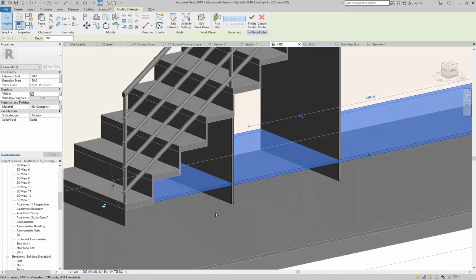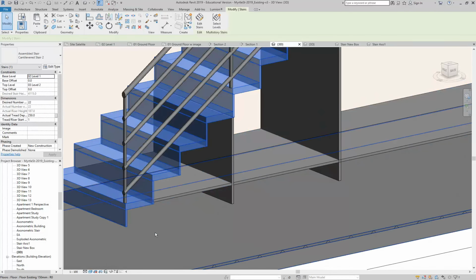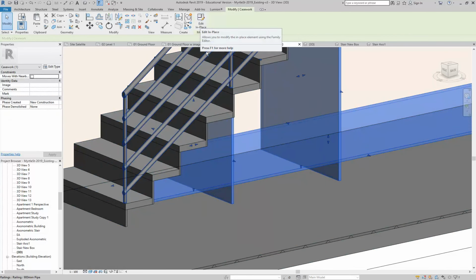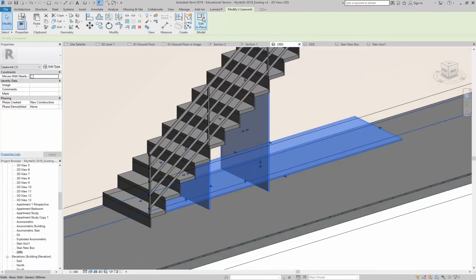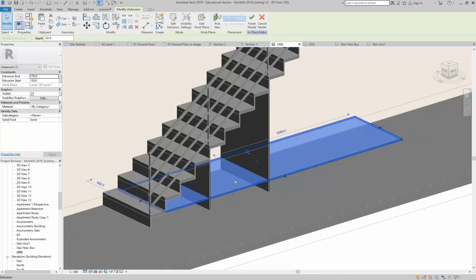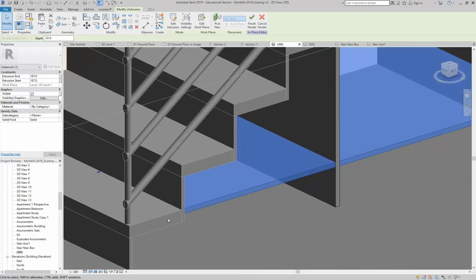So how do you check that? Go and have a look at your stairs. And we can see it's 187. So remember, when you're working with things that you've modelled, you need to go to Edit in Place to change them. Don't go back to Model in Place. Okay, so here I could start, also I'll end at 187, and then I'll come down 20mm from there. So this will be 167. And that's going to line up exactly. Or I could try and even make the thickness of the shelves the same as my treads. Got all those different options.